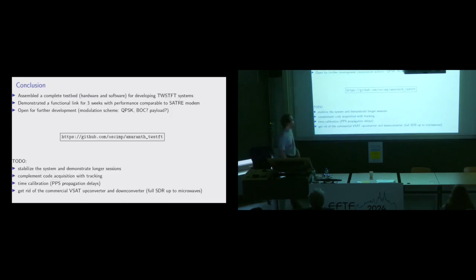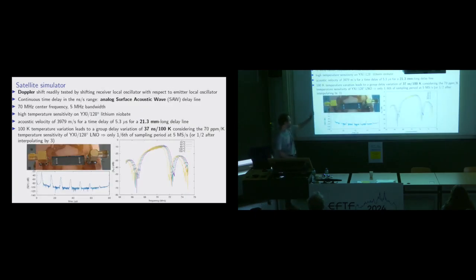And so you can, okay, that's not yet updated. So you can have a simulation where you're, I can send you if you're interested. So you can do the simulation, warm up the lithium niobate, introduce a few nanoseconds per second time offset, and it allows you to perform the simulation of not only the frequency offset, but also the time offset.